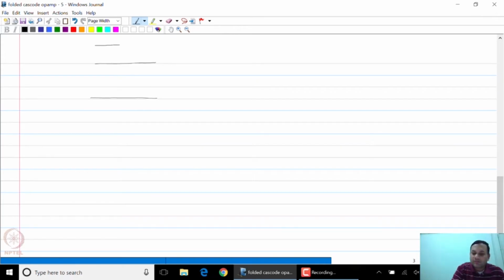So this is VDD, which is 3 volts, and you are giving slightly more than half of that to M9 and M10, 0.5 volts for M9 and 10, and we have now given 0.4 volts for M3 and 4. So that means your maximum voltage at the output can be 2.1 volts.